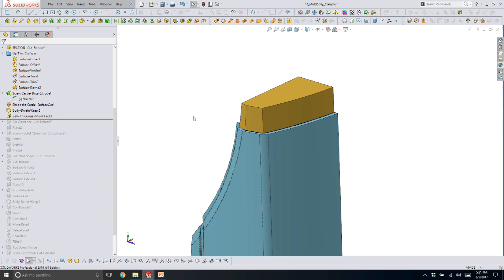If you see that zero thickness error, check along the faces of the parts that are intersecting and maybe add a move face to them. I've also seen combine, which we use to put them together, fail sometimes when surfaces are line to line with each other. So if I'd done a zero offset replace face, for example, try and just have everything pierce in a little bit by 0.5 millimeter, a millimeter, 20, 40 thousandths, and you'll be A-okay.